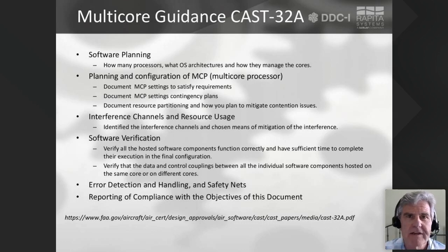For any DO-178C certification, you're going to have to provide evidence of analysis for timing and structure of your system software and design. If you've done safety critical before, you've done these analyses and provided the appropriate artifacts. Today, we want to discuss the analysis of worst case execution time in the multi-core environment, identifying and mitigating interference patterns that affect the WCET to have disastrous results.